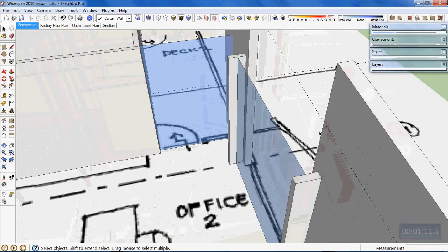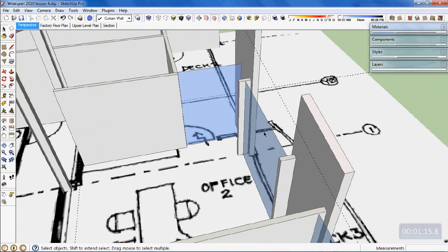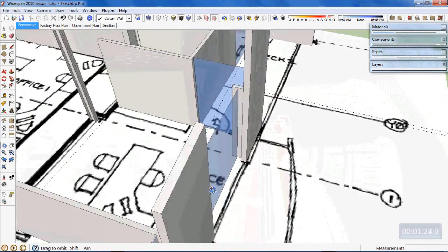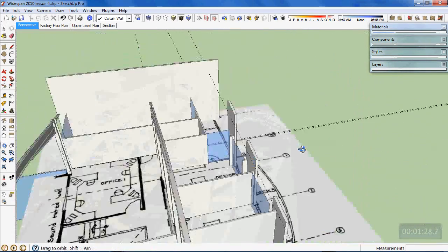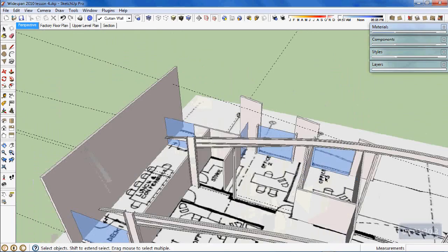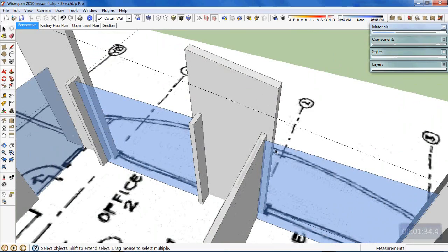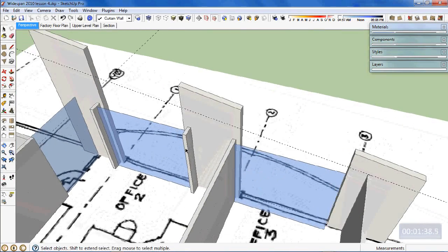So therefore, our glass curtain wall, for a door opening and window opening, would need to set back from there. That's why I've done these little nib walls. They'll just be 92mm framed walls, with the glass curtain wall sitting in between. So I should do something similar over on this side, although this wall looks fairly close to that already. We'd need to do something similar to this wall here.